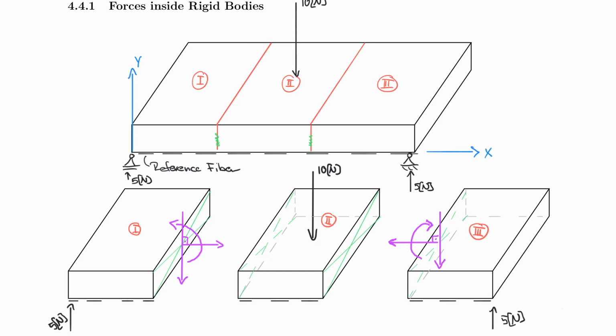And one important thing to note is if I put the first surface into equilibrium, let's say for the vertical forces, then yeah, you may think that now this could be in equilibrium because I have something pointing up and something pointing down. But notice once again that these two forces actually rotate the system. And even if I bring in a moment here on this side now, it could still rotate the system.